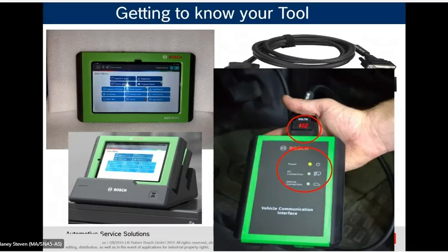That'll power the VCI up, and then you can still get through your scan, and maybe you can worry about why you don't have power there later. The next one down, the middle one, is PC connection. That just lights up and tells you that your scan tool or your laptop, depending on what kind of work you're doing there, is connected, and it sees it.